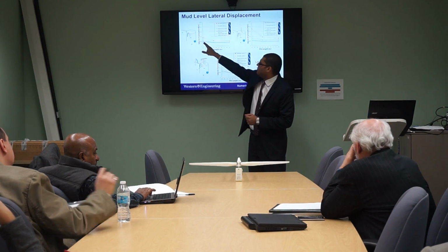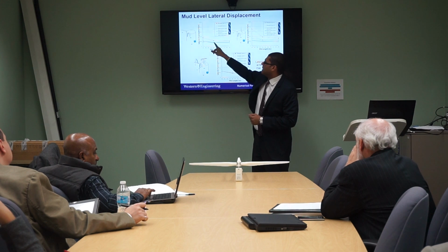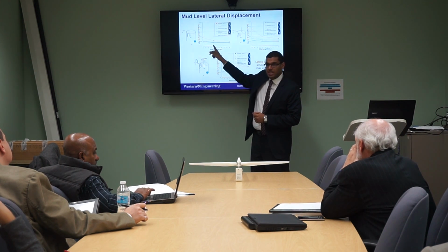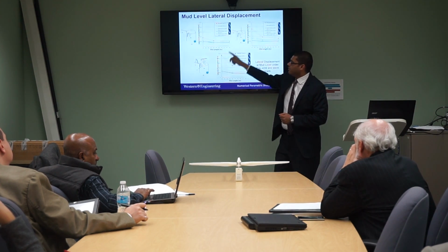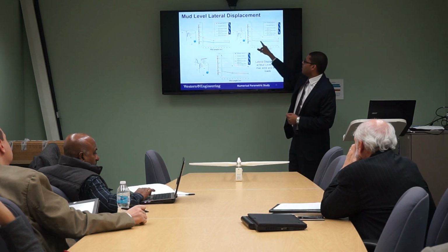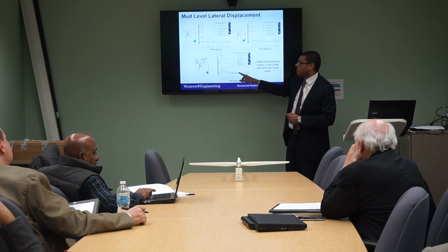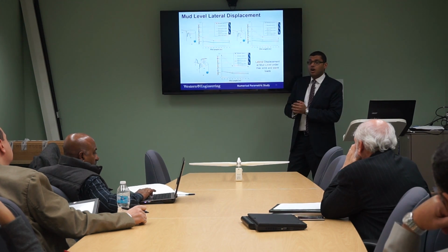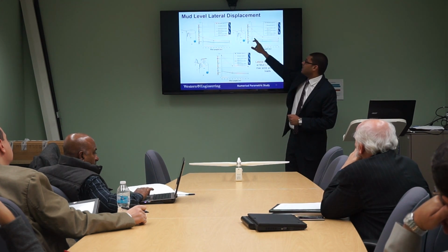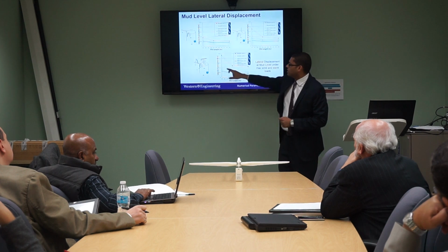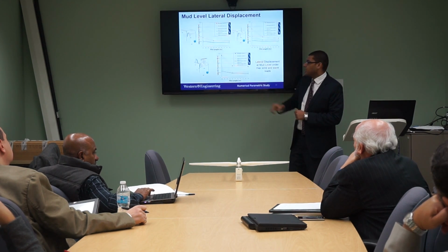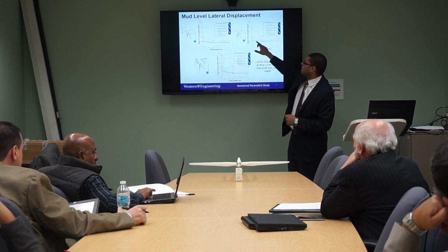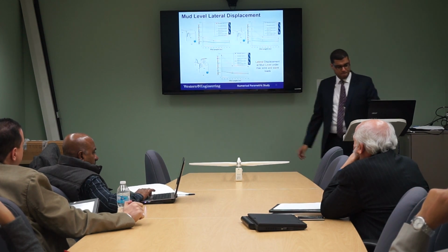The hybrid system is better than the monopile till 24 meter length. But after adding the different components, the hybrid foundation system is better than the monopile with 6 meter diameter. So our hybrid foundation system with pile diameter 4 meter is better than the monopile with diameter 6 meters. We can see the displacement here.